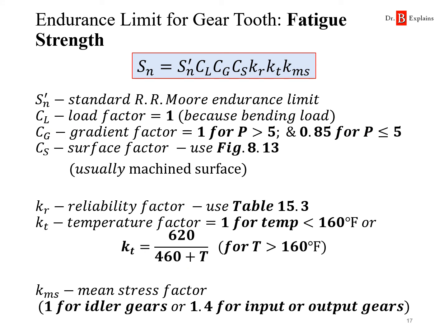So the previous equation, with all those factors, we use it to calculate the bending stress on the tooth, right? If we want this gear to last forever, we need to make sure that those stresses never exceed the endurance limit of the material that the gear is made of. And so we can calculate what the endurance limit is specifically for the gears by using this equation, which looks a lot like the endurance limit equation, but it has some additional factors, or slightly different ones, specifically for the gear application.